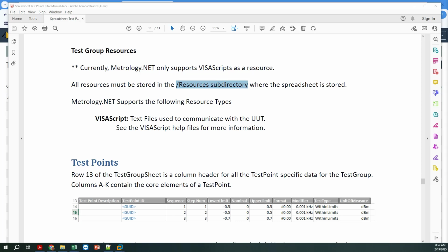Because here's the real world problem of that. When you're calibrating a Keysight oscilloscope and you want to measure the 1 meg input, they tell you in the manual to use the 10 meg range of the 3458. So now the unit under test has to have knowledge of the standard.